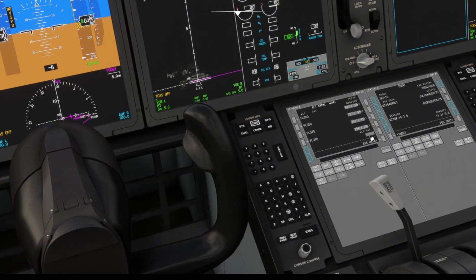And you can add a temperature. So for example, when I check my chart, I'm gonna use flight level 350 / temperature -51. So now basically this calculates the assumed temperature for those flight levels according to the standard lapse rate, which is -2 degrees per climbing 1,000 feet.